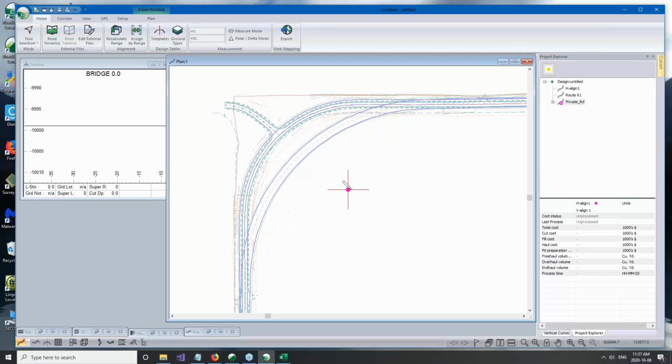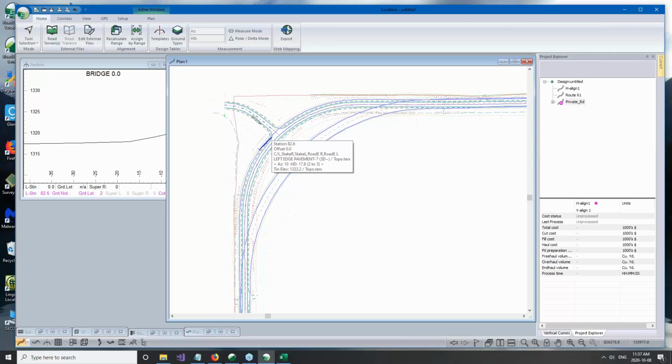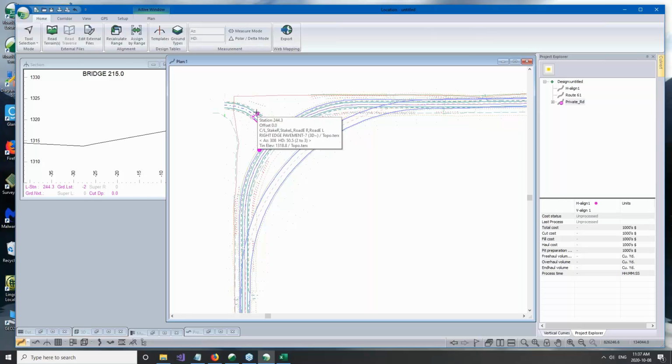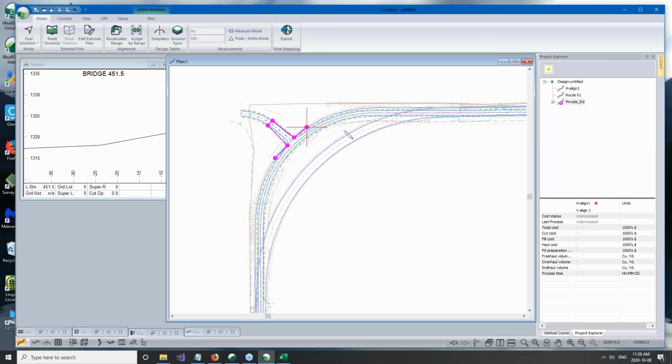And now I'll quickly create an alignment in there. I'll come there somewhere, and then there, here. So I'll just model it back, because when I calculate my cross sections, they're going to be perpendicular to the alignment. So I'm only going to be really modeling it in a cross-sectional way. If I wanted something more three-dimensional, I would have to go back to the terrain. So there's a driveway coming off.